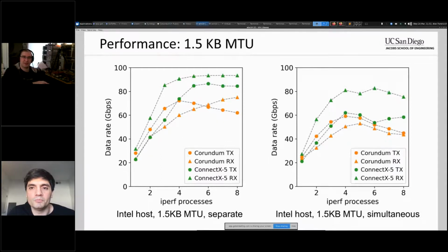So yeah, we have the PTP clock, and then we take that and synchronize it into all of the transmit and receive clock domains for all of the Ethernet MACs, and then those MACs will timestamp all of the incoming and outgoing packets, and then those timestamps are passed back to the data path and included in the completion data that gets handed off to the operating system. So we have a PTP clock, and then we provide hardware timestamps for every single transmitted and received packet. And I think we're providing those with a 1 nanosecond resolution. I think we threw out the fractional nanosecond field just to save space in the completions.